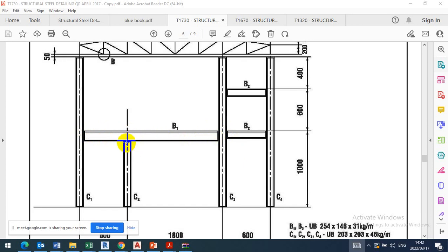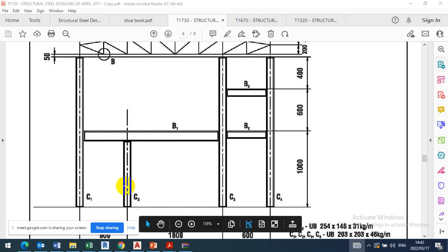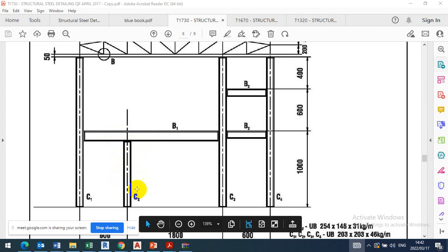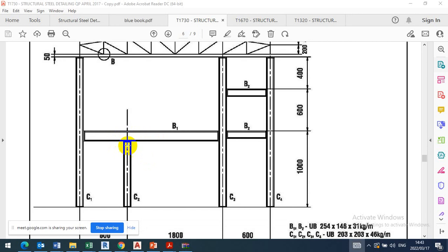But when the beam is connecting to a column like this, this is a column to beam. Because the beam is big, then the column is here. We don't show the cap plate because there's a cap here. The cap will come with a column. So the detail of the cap plate will be done when we do a C1, if ever they want detailing of C1. But what do you show on the beam at that position? It's only the bolt holes position and also the flange thickness.